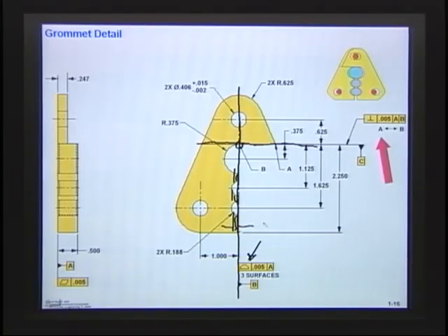That zone of tolerance right there was 5 thousandths, right? And all of those zones are hooked together. Perpendicularity wouldn't hook them together, so I used a profile there. This one here I used a perpendicularity, so it's possible that this surface could come in something like this right on the datum feature. And it could be off no more than 5, but when I put my mating part on there, that's no more than 5. And remember, we had to have a gap of 10, so that's where this 5 thousandths came into play.